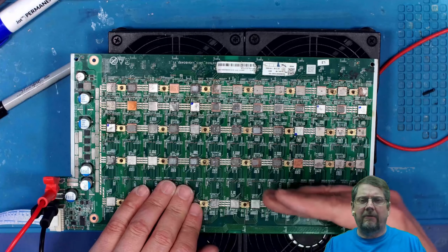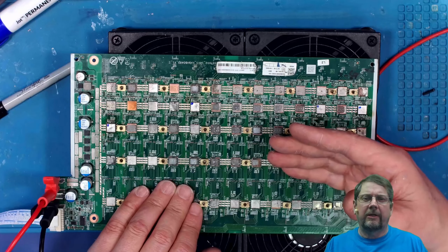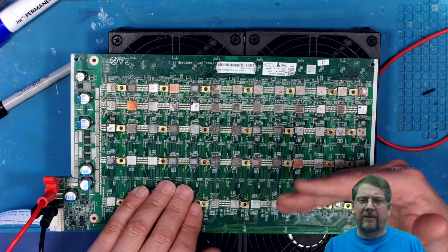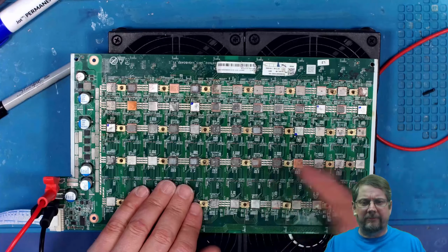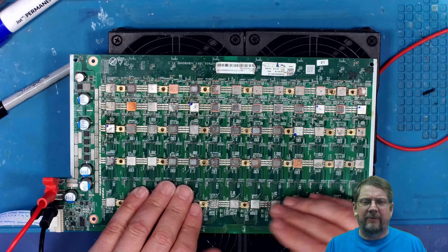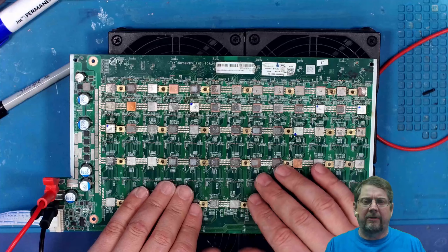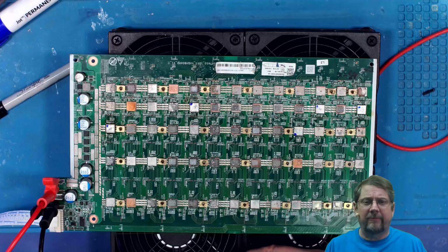So if I had already pulled the chip and I could recognize it, because usually it was a cleaner solder job in those cases, just refresh the solder and then keep moving. There's no reason to strip the solder every single time as long as it's not unleaded solder. Unleaded solder you always want to take off before you put leaded on.